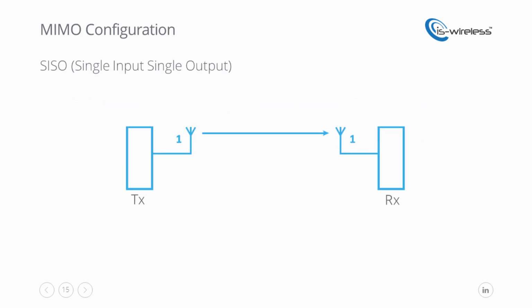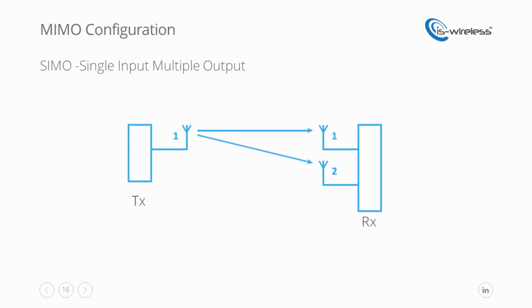Now we'll look into the configurations of MIMO. Each of them has different advantages and disadvantages. Consequently, network designers can choose accordingly to their needs. The first and the most basic radio link is called single input, single output. Here, the receiver and transmitter include only one antenna. This model is used in GSM systems, satellite or CDMA. The advantage of the following system is simplicity, while the disadvantage is high susceptibility to the interferences and fading.